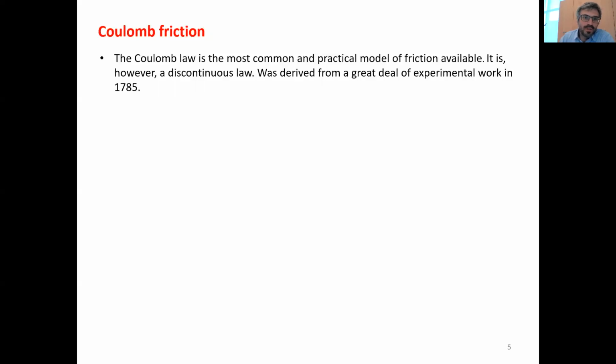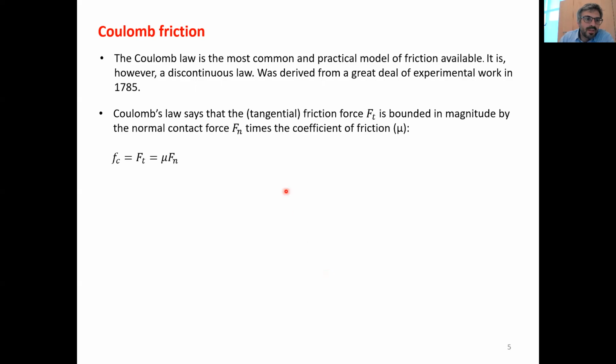It's very old, derived with many experiments back in the 18th century, and the Coulomb law says that the tangential force during a sliding motion is bounded in magnitude by the normal force at the contact, by a fixed ratio that is the friction coefficient mu.